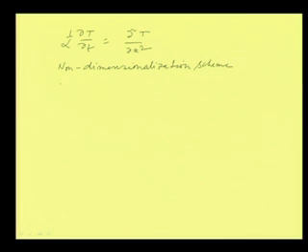So, we say that y is equal to T bar by Ti bar. We have already seen what T bar is: T bar is the reduced temperature at any location, equal to T minus Ts, where Ts is the surface temperature when it is exposed to the cooling environment, and Ti bar is equal to Ti minus Ts, where Ti is the initial temperature of the solid body of concern. Then x will be non-dimensionalized as x bar, equal to x by L, where L is the total length along the x direction.